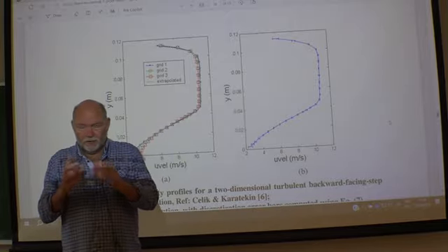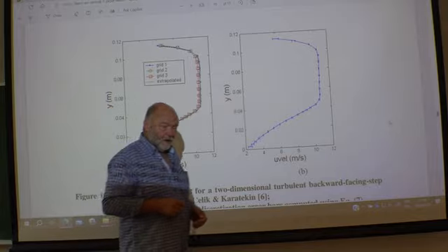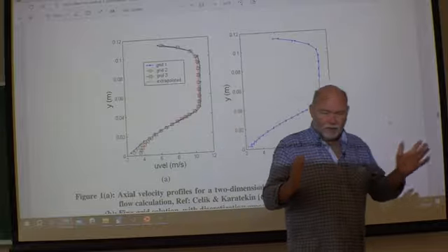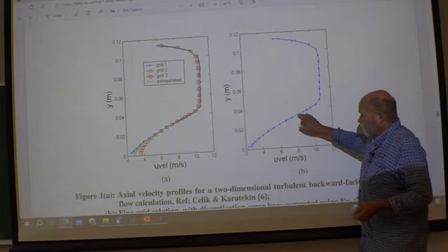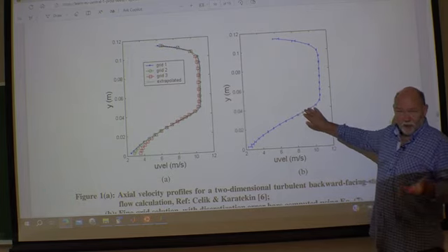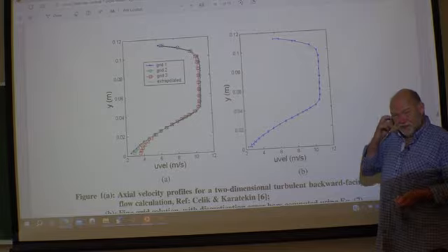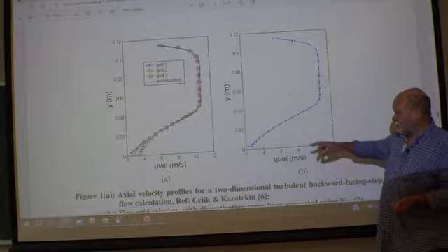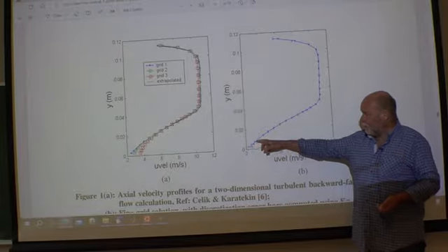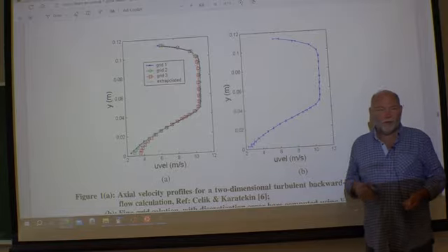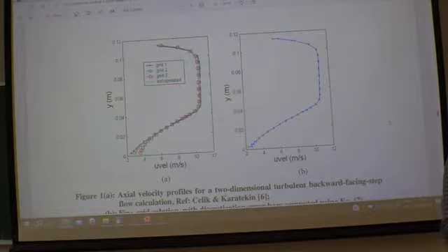How can you do that? We only had one GCI, and that was actually not for this velocity profile thing, but for the reattachment length. Well, if you want to do it like this, and this is very nice indeed, this is the way it should have been done, but to find it, you have to use your GCI procedure for every single point where you want an error bar, because you have to find the local error at that point for that monitor value.